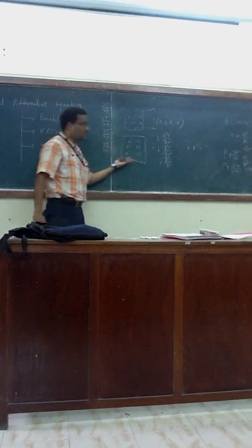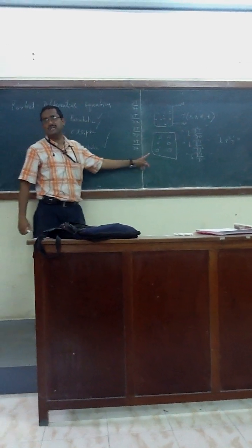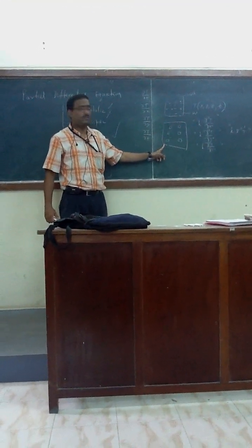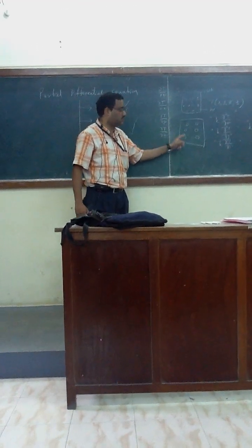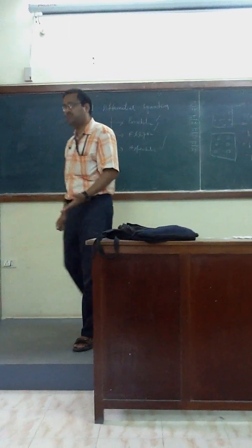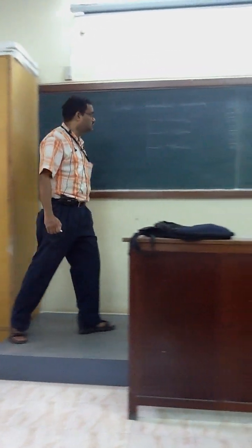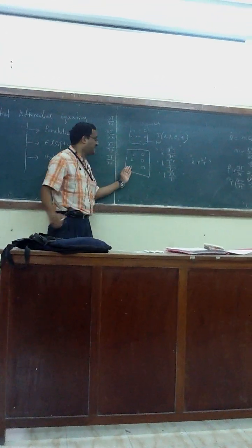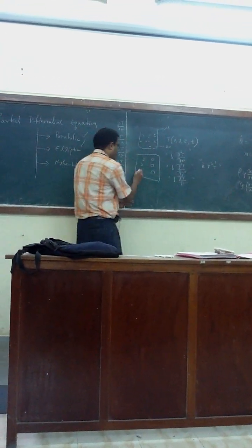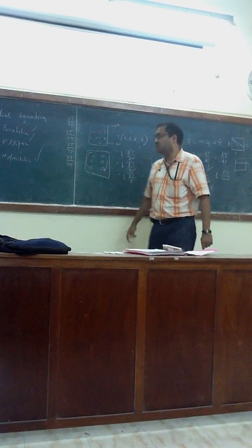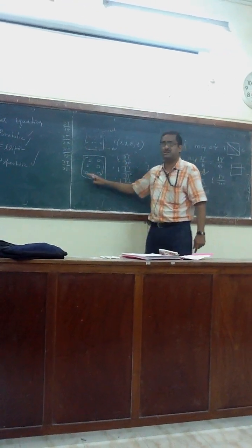Why? Because here the temperature is very high, the density of the fluid is much less. Buoyancy. We know the density decreases with temperature. If temperature increases, density decreases. So this fluid particle will become lighter compared to this. This fellow will be going here and this fellow is coming here. With that, the temperature also will change point to point.